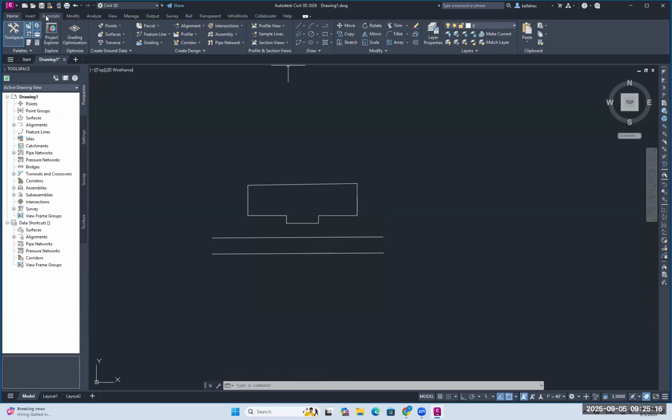All right, one of the last things I ask you to do is a little bit of annotation. So two things I want to show you. Text. If I want to write on here Markle Hall, I'm going to click. It's going to allow me to specify the height of that text. Let's just take the default 0.2 and a rotation angle of 0. We can always rotate it. I'm going to call this Markle Hall. I'm going to hit enter, and then I'm going to hit escape.